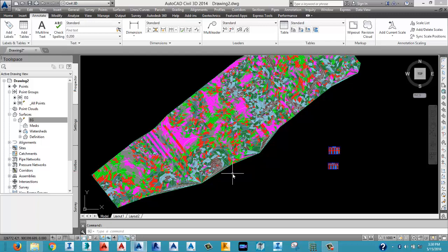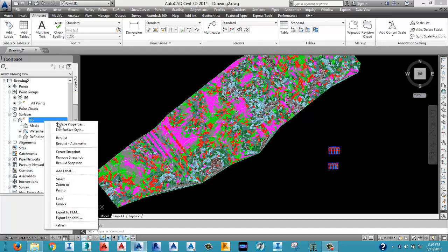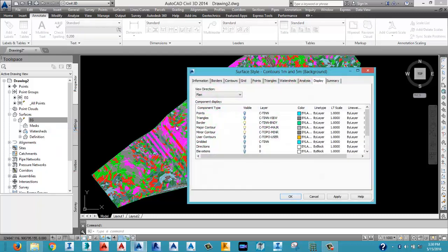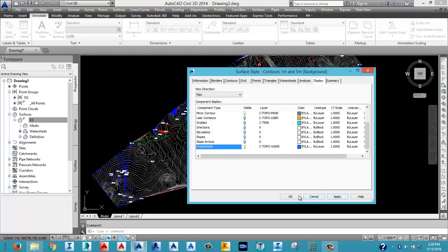Yes, run it. 6 or 8? 8, I put 8. So the same way we did for the subsequent ones, you have to go turn the light on for watershed analysis. Did I merge adjacent boundary? No, don't check that. So I click on my watershed, apply.